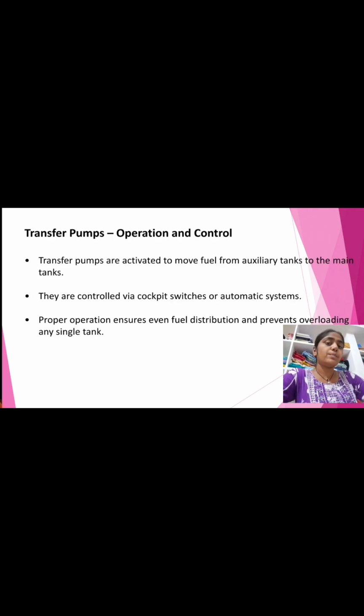Transfer pump operation and control. Transfer pumps are activated to move fuel from auxiliary tanks to the main tank. They are controlled via cockpit switches or automatic systems. Proper operation ensures even fuel distribution and prevents overload in a single tank.